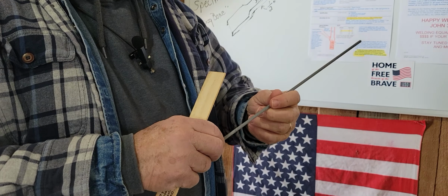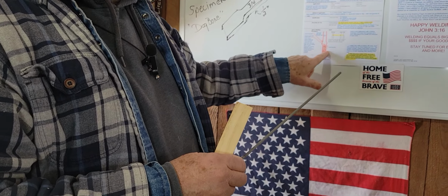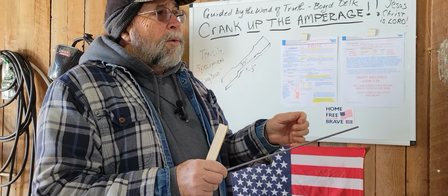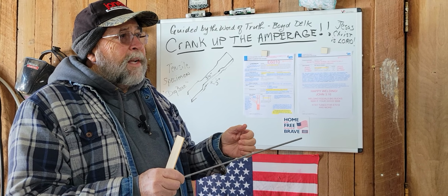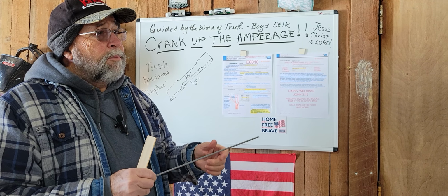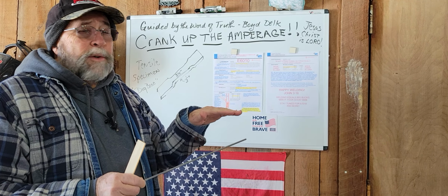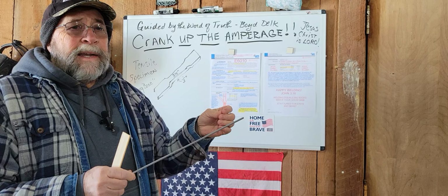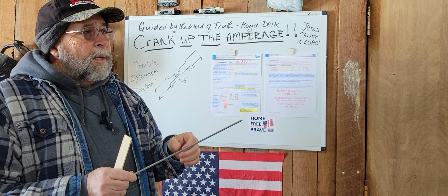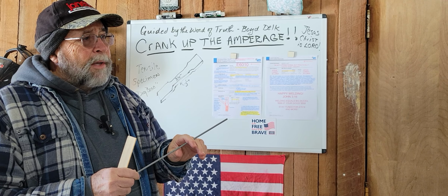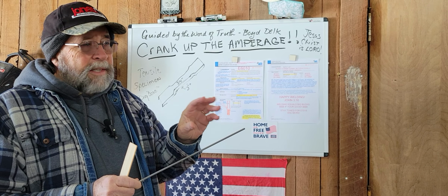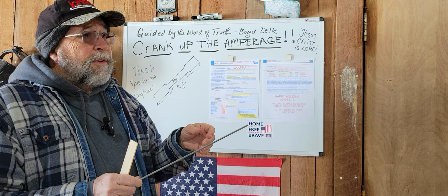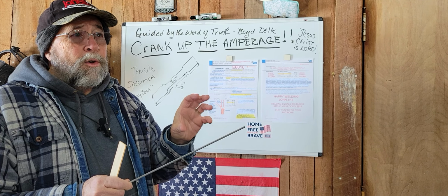So I like to weld when I'm doing an open butt root pass, for example, and we'll get into that down here. I like to use lower, colder amperages with an arc force or a dig of a +1 or +2, generally a +2. What that does is allow you to decrease the amperage, increase the dig to dig into the base metal, and maintain an arc at colder amperages. It allows you to slow down, focus more on the puddle, and put the metal where you want it to go. Exactly. It's just amazing. I will do some videos of me doing it in the future so you can actually see it being used on a weld or in a weld.